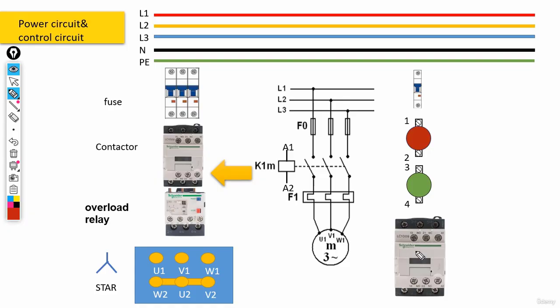Well, if you remember, we had a couple of terminals here called 13 and 14. We need to connect these to our start push button. Let me just draw the sketches that I had before. Okay. Now, what we should do? Well, 13 would be connected to 3 here. And 14 would be connected to 4.